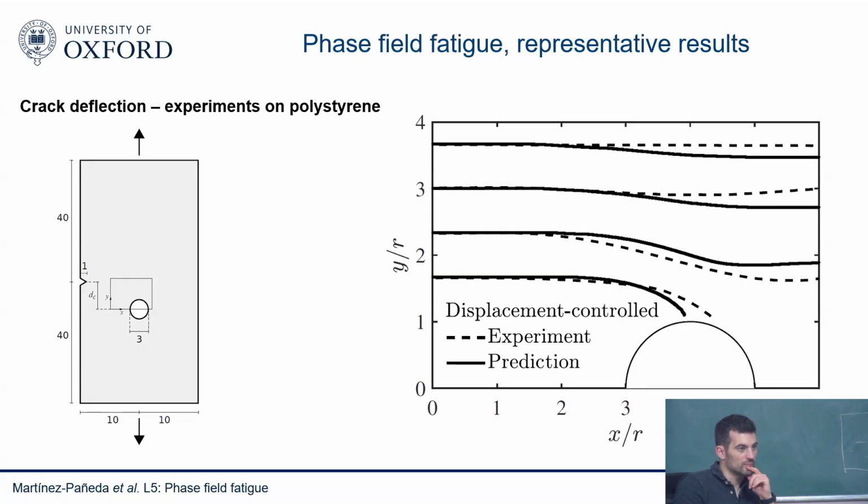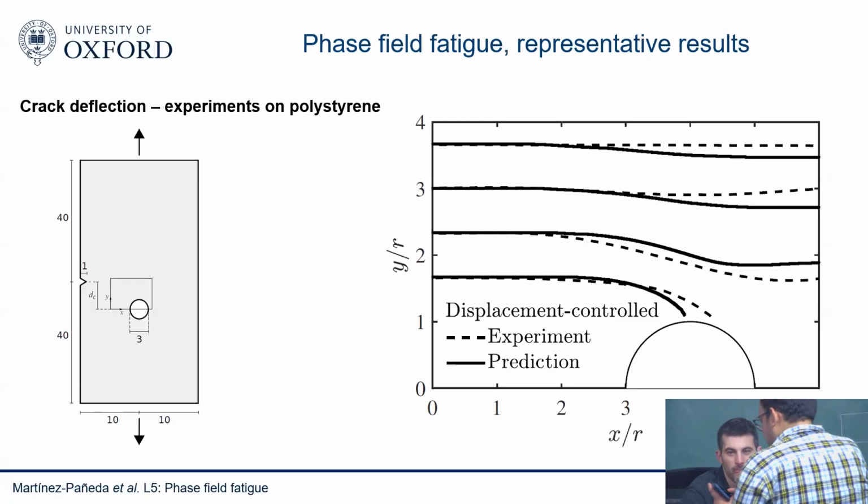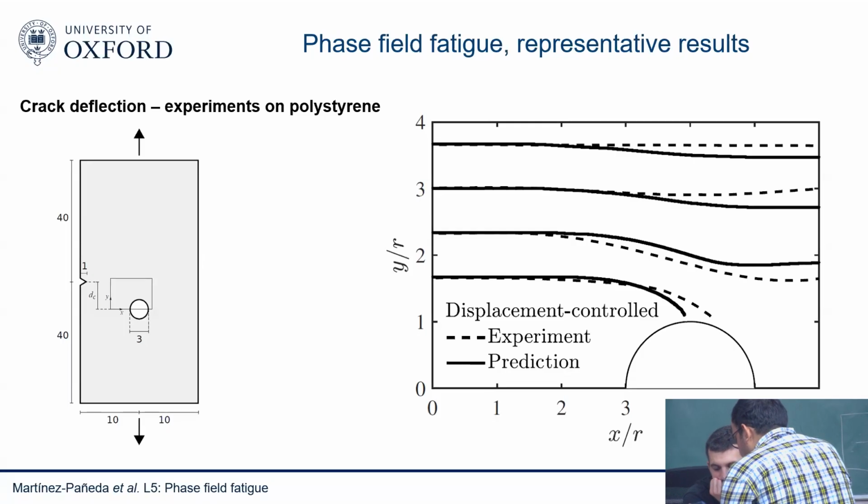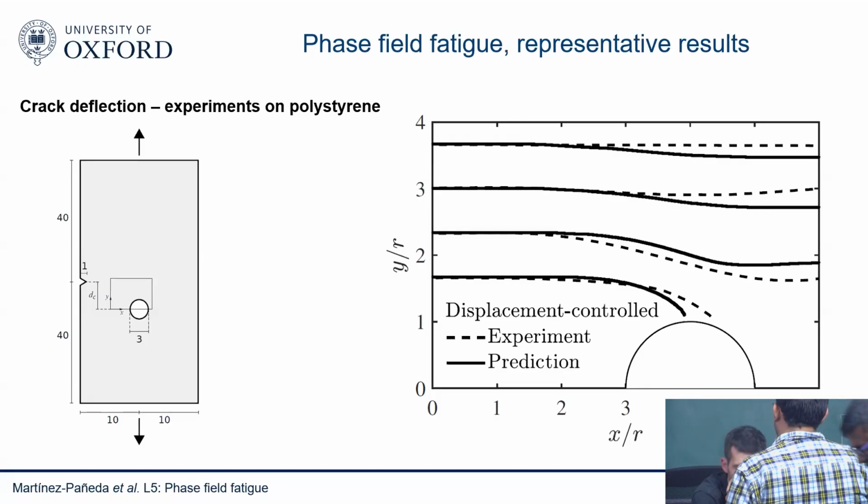I'm not able to find that, but I have some other video. In this case, I had the crack through the hole, but in this case also it was symmetric. We were doing this in photoelasticity. In this case, it will follow a straight path. But when the crack tip is between the holes, it will move towards one. Yeah, interesting, it will be interesting.